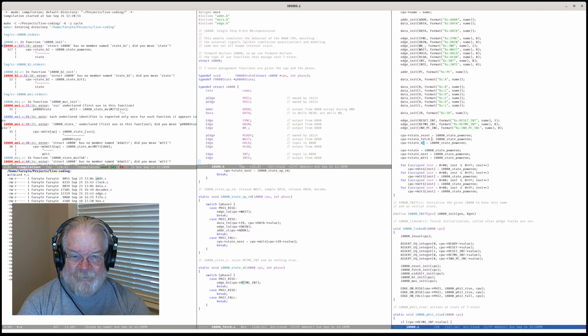So now, MVI init, I do need to make this at least compile. And let's look up the correct MVI instruction. MVI is hex 3. No, it's hex 06 with the destination left shifted by 3.